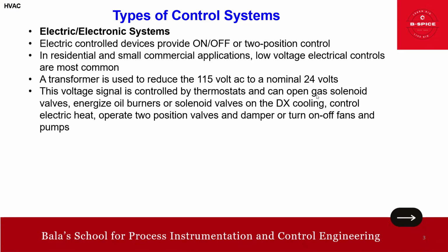I think there is a typo error. Yeah, correct. It can open solenoid valves, energize oil burners or solenoid valves on DX cooling. Okay, this is nothing but direct expansion cooling actually. So if you want to know about this, I can also update you on DX cooling. So DX cooling, or direct expansion cooling, is a type of air conditioning system used in HVAC. In a DX system, the air used for cooling a space is directly chilled by the refrigerant in the cooling coil.